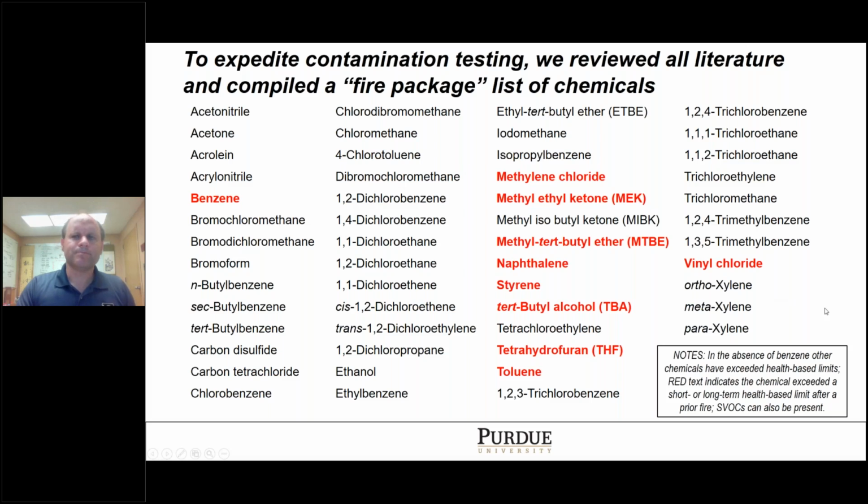Now, some guidance that we provided to the community out in Colorado and Oregon, as well as California, is identifying which chemicals they should be testing for. So initially, after the fire, you're looking at safety, power, and pressure. And as you restore pressure, then you're looking at bacteriological integrity of the system.